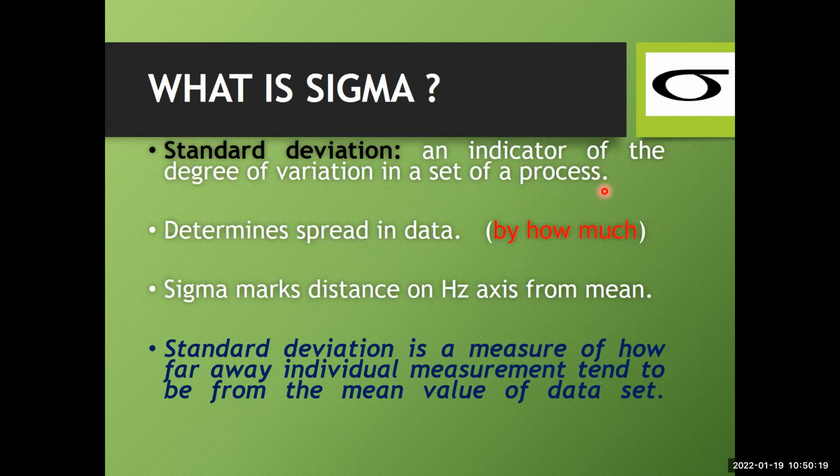Suppose you are a manufacturer of a shaft of 100 mm in diameter. So what is the target value? 100 mm diameter shaft. Every time we do not get that 100 mm due to several X factors, noise factors present in the system. Sometimes I get 99.99, sometimes 100.01, 100.02, 100.03, 99.9897. Very few times do I directly hit the target value of 100 mm.